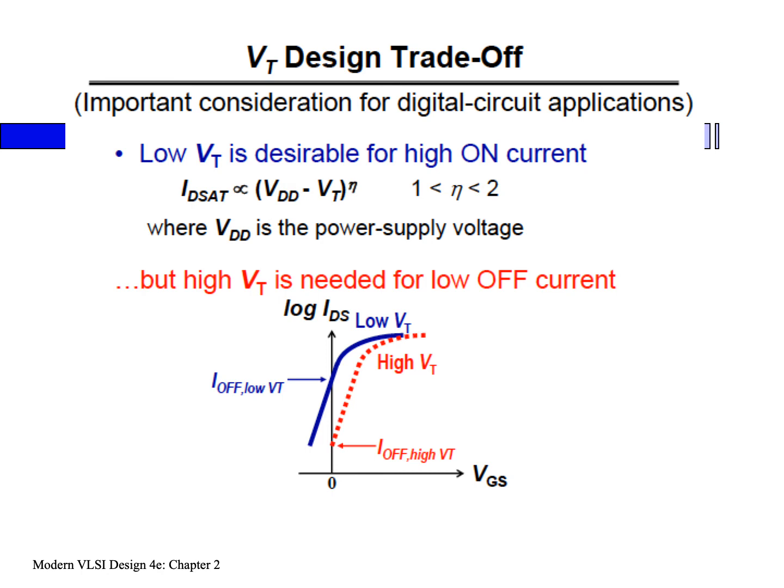So we have this dilemma in the design, because for a lot of low power designs, we want to reduce VT because we reduce supply voltage. Accordingly, we need to reduce threshold voltage to maintain the so-called noise margin, but that hurts leakage current. So we cannot satisfy both the leakage current and the performance of the device in the active region.